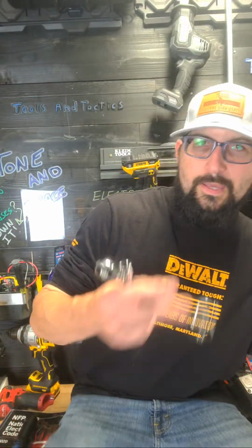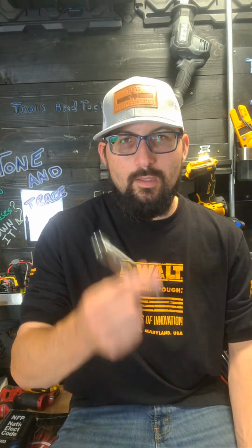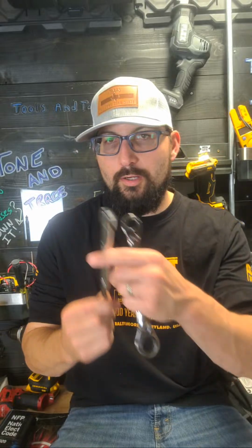This is the thought on the Klein stuff. The pass-through ratchets. Do you need the pass-through ratchets from Klein? That's the big question. This is your answer. When you're building a strut rack and you've got a nut on the top and a nut on the bottom, for the most part, you can spin that nut by hand all the way up the all thread. And then you can get a longer, deeper socket like this Klein, put it on your impact, do one bump, and it's set.